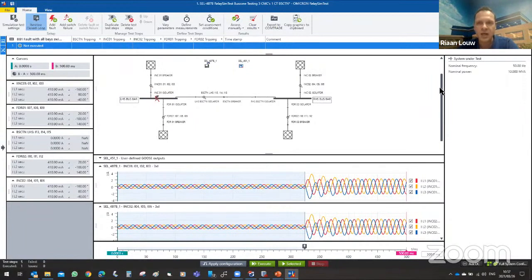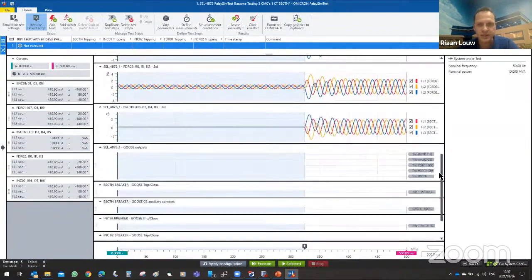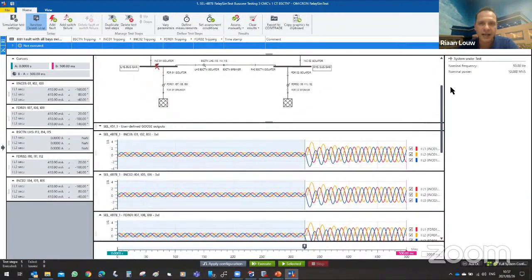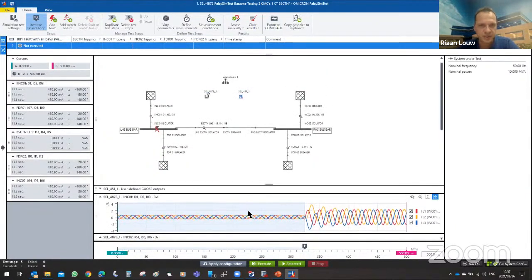Now recognize how my system looks different in the transient side of the simulation. So here now I can see there's 2 conditions here. There's the pre-fault and there's the actual fault condition. You also recognize that obviously the current flow significantly increases as there's a fault. I'm simulating a 3-phase fault, so all 3-phase currents are adjusted accordingly.